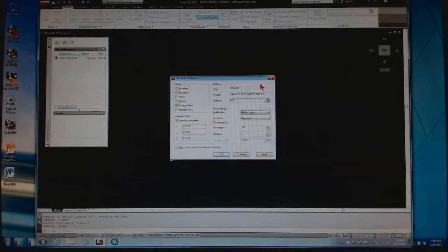you were putting attributes inside of a block, like say you drew a couch. A company you work for is some type of furniture manufacturer. And the couch you drew, they wanted you to put attributes in it like what is the manufacturer's name, the cost, the type, what type of fabric, color. Let's say you had to do all that. Every time you insert it on the drawing, you really wouldn't want all that to show up, would you? So that would be a time when you would want that kind of information invisible. For this purpose, we wouldn't want this invisible.